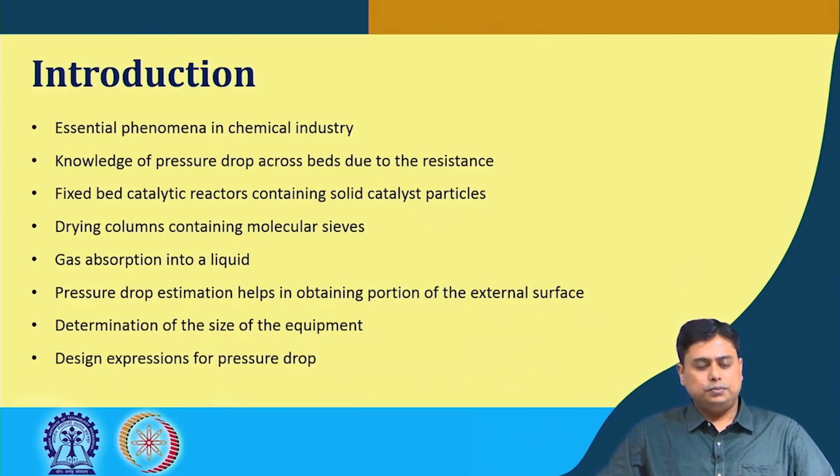Okay. So the essential goal in this section is to understand how the pressure drop will vary when a fluid flows through a stack of particles or a bed of powders, particles having different sizes, particles of different shapes and similar things.